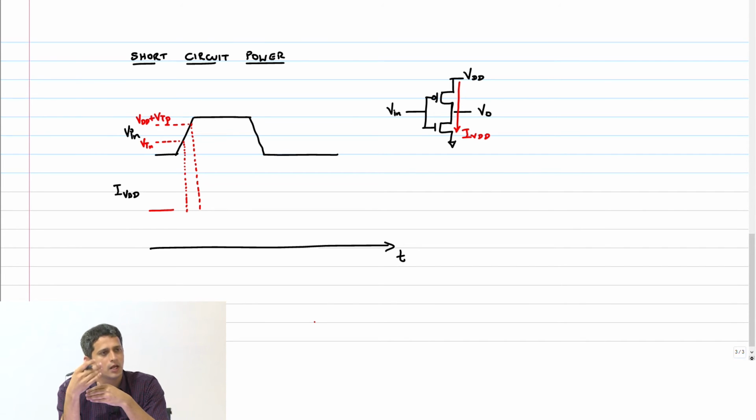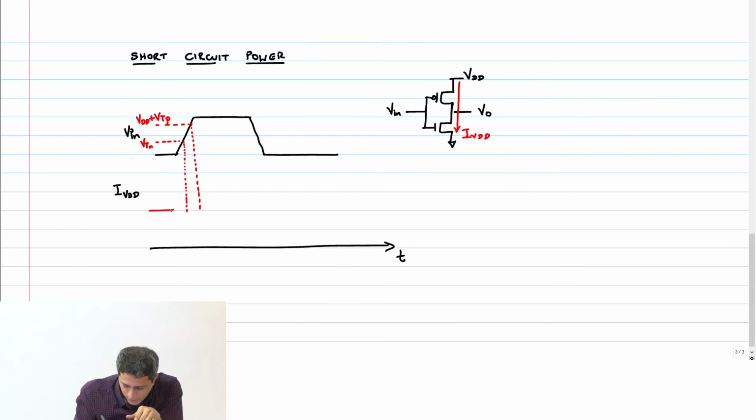After that, again the PMOS starts going into saturation, NMOS will come into linear, therefore reducing the current, and then back into cutoff. So in this region, you can approximate the current as a triangular region like this, right? And this we are going to call I peak, IP.